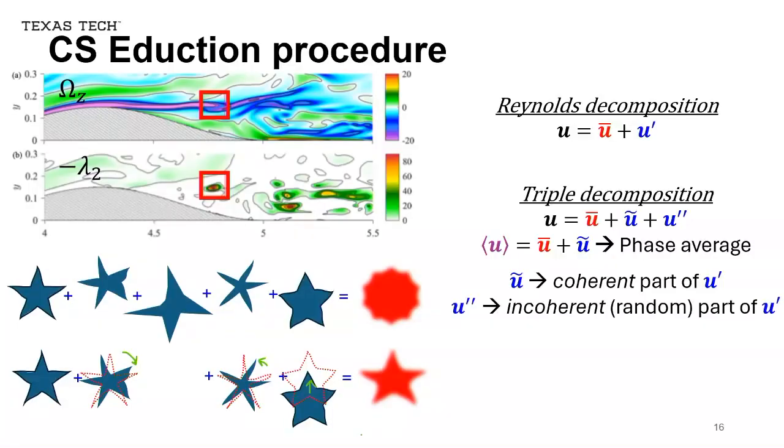So you have to go back and discard those structures that do not correlate well with your first ensemble average, such that you can refine this process and actually obtain a sharper, more coherent structure by removing those realizations that do not correlate very well with the ensemble average. And this is an iterative process until there are no more realizations being discarded, and then that's how you decide, okay, this is the coherent structure of the flow.